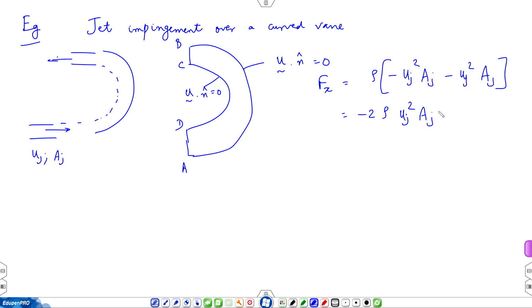Well, on the free surface it is atmospheric pressure, everywhere it is atmospheric pressure. Okay. So, pressure there is no, this is external flow. So, unlike internal flow problem of the bend, here there is no contribution because of pressure.